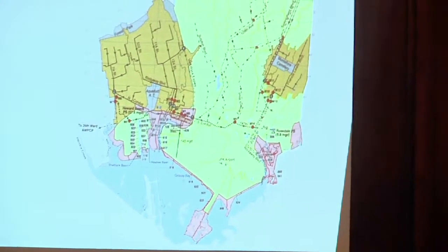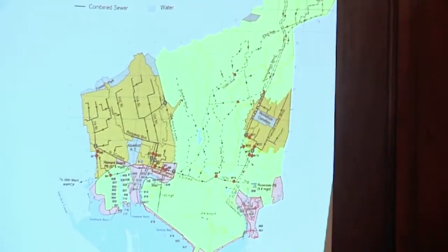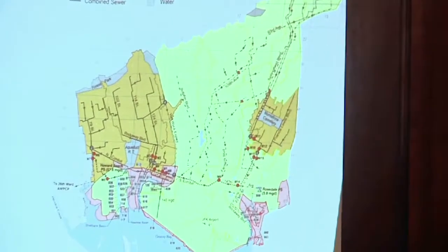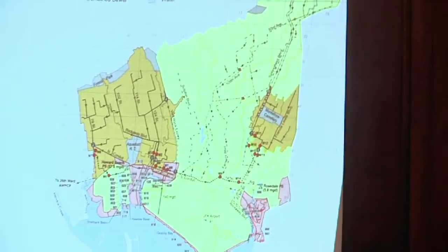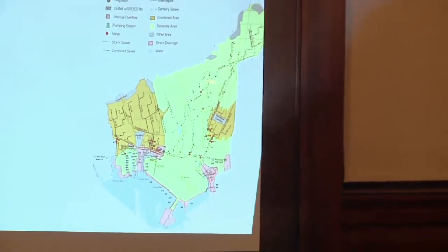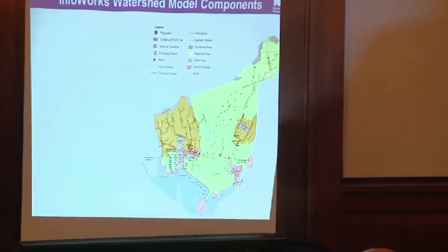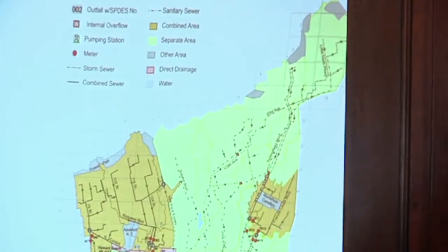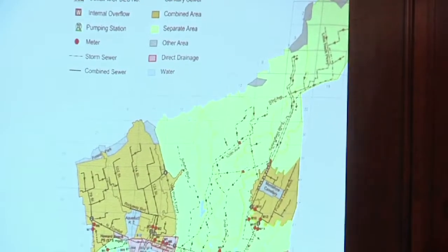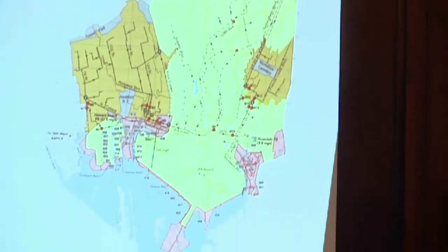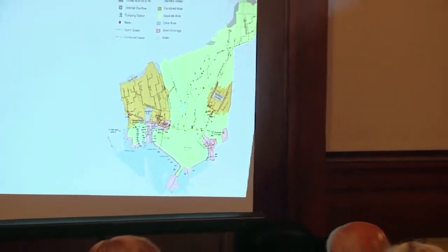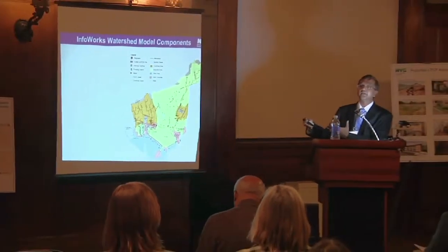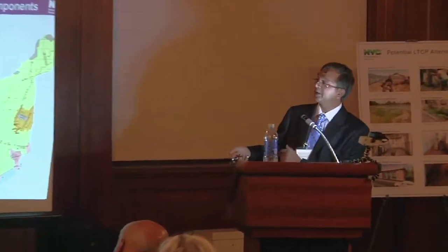New York City has over 7,000 miles of sewer system, so not every sewer is built into the model. Generally, 48 inch and larger pipes are included. What you see here is that network taking the flow from upper portions of the system towards the treatment plant. And all the control elements, like the combined sewer system, interceptor sewers, the regulators, outfalls with tidal boundary conditions, are all included in the model to account for the dynamic conditions that happen within the sewer system.